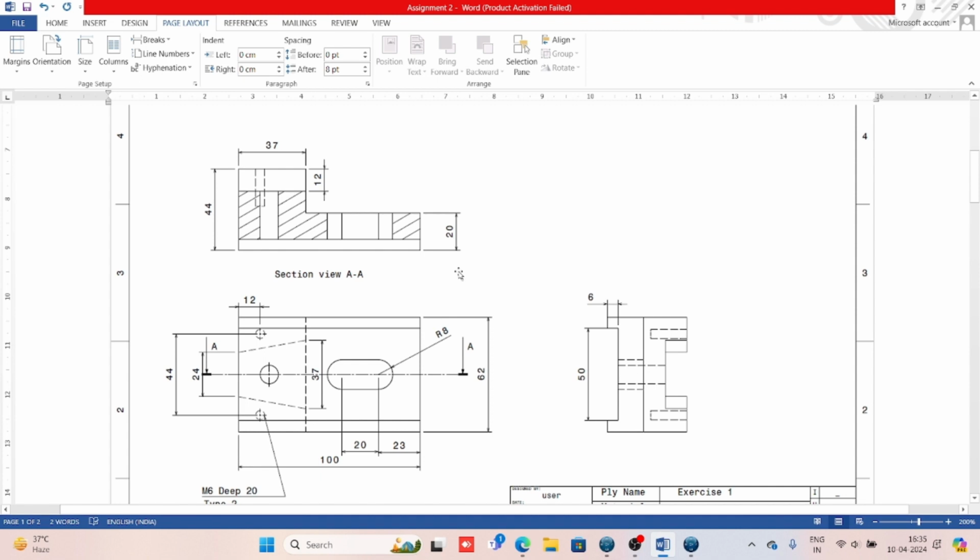In this drawing the center hardly matters, but anyhow we have to make our drawing fully defined, so we have to pick a point where we can define our zero. I have planned to make this drawing with the help of a centered rectangle, so that is the reason I am choosing this point as 0 0, because the center will lie somewhere here.